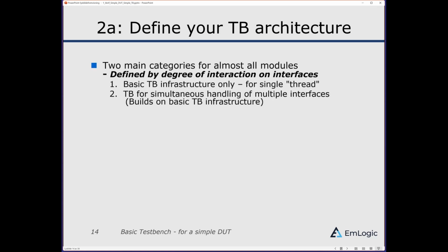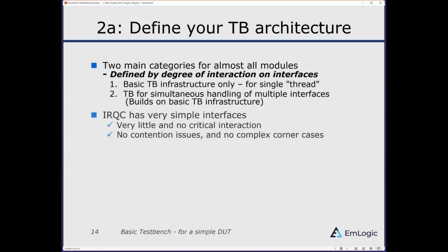So first, let's look at how to make a verification specification. In my opinion, this is always needed, but it doesn't need to be too extensive or detailed for a simple device under test. And also, sometimes you don't really need a dedicated specification document. So in this case, for instance, for the interrupt controller, this could be at least an initial list for a verification specification. This is basically in order for you to show other people on your team that you have thought of everything and these are the things I'm going to try to verify.